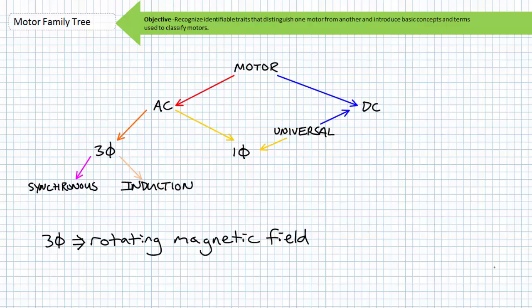The term synchronous speed is the rotational speed of the magnetic field. It's a handy reference point for the speed of the motor, which we'll see in a little bit may or may not be synchronized with the synchronous speed, or may slip behind it, or ahead in the case of asynchronous generation. The synchronous speed can be determined by the input AC frequency and the number of poles per phase, or as I prefer, the AC input period and the number of pole pairs per phase, since the north must accompany a south and vice versa.